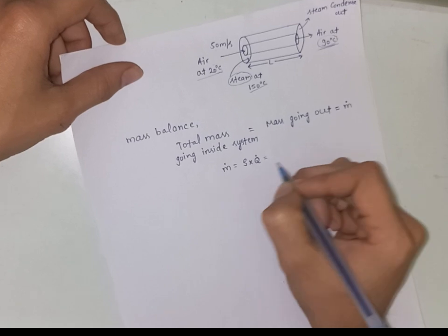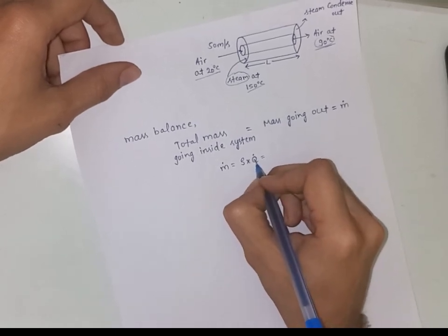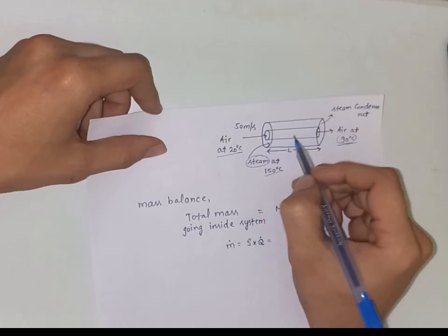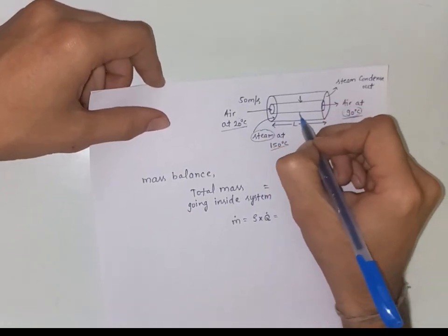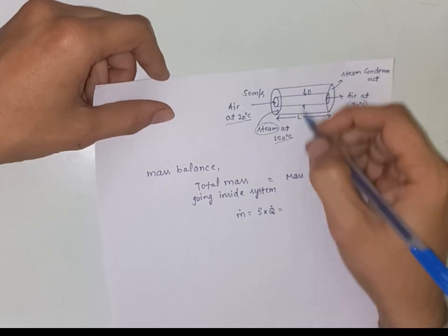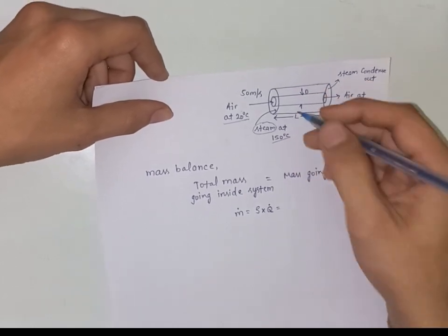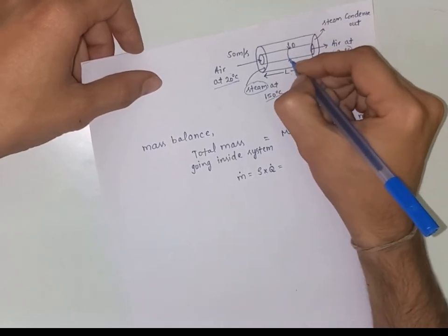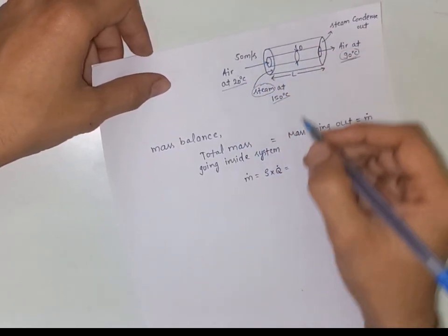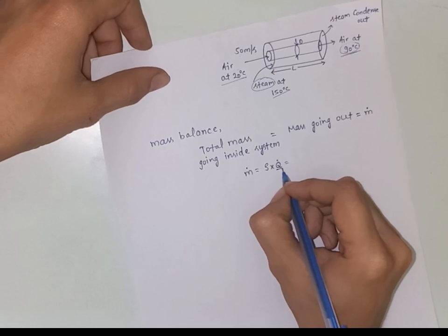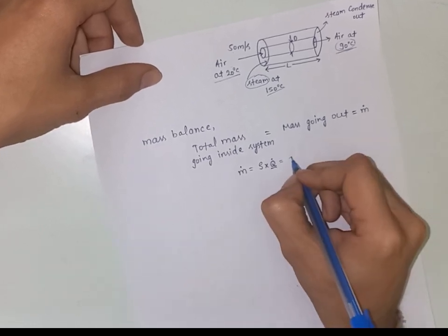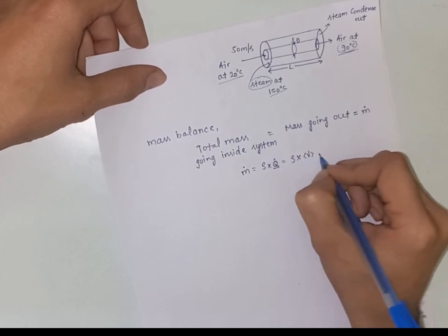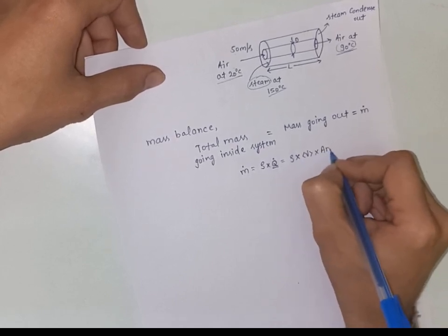Further, if we don't know the value of the volumetric flow rate, we note that this is a circular cross section with a diameter, or radius, of the circular cylinder. In that way we can find the area of that, and we know the velocity. So we can write the volumetric flow rate as velocity multiplied by the cross-sectional area.